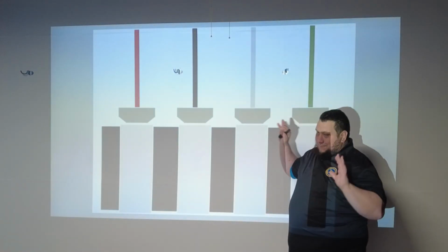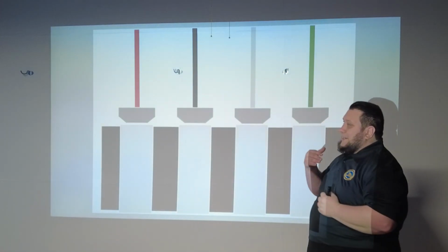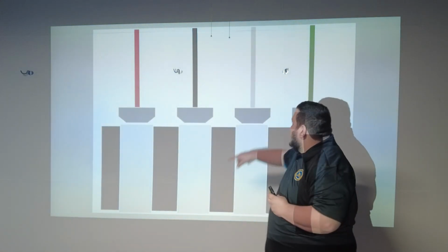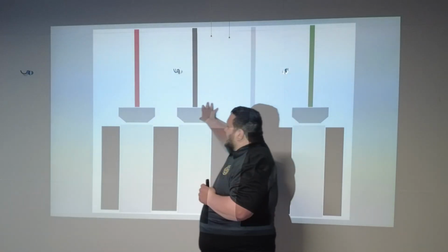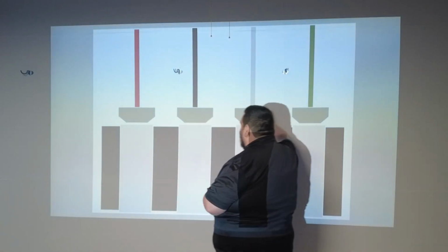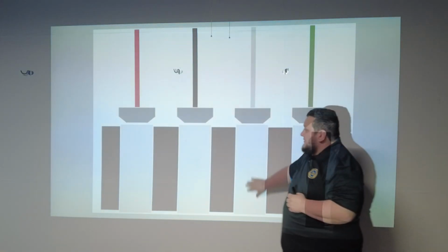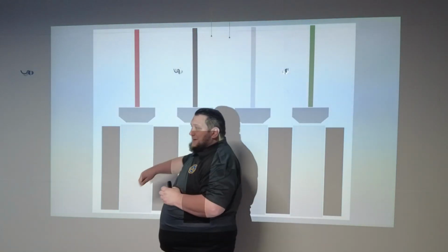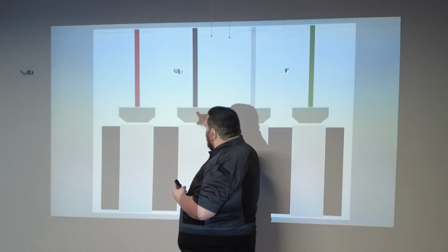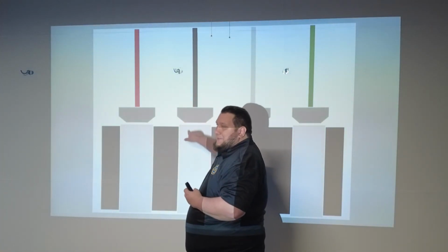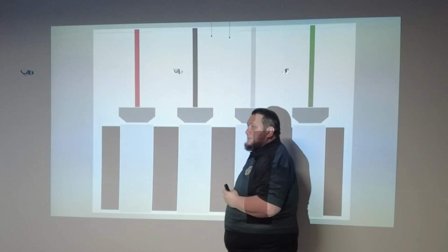This complicated looking diagram is the inside of your shore cord reel. Right? So this right here is your cable for your shore cord that's going out, and it makes contact on the inside with a drum. The drum has metal contactors on it. So as the drum rotates, those wires are making contact here, providing that power to the rest of the RV.